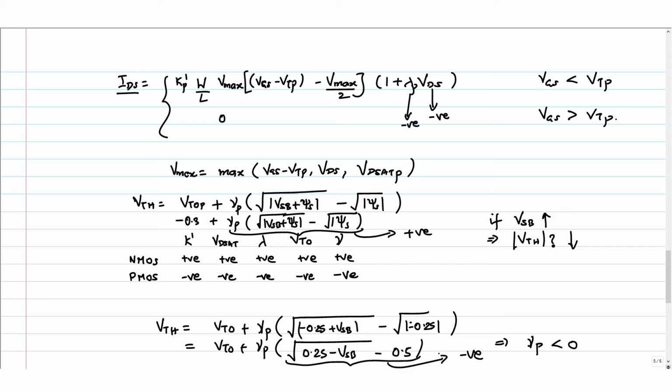This is very nice because all parameter values are positive for NMOS transistors and all negative for PMOS transistors, but you should know why they have to be negative. And there are some catches like this, especially for PMOS. Substitute values and remove the mod, otherwise that analysis will go completely wrong.